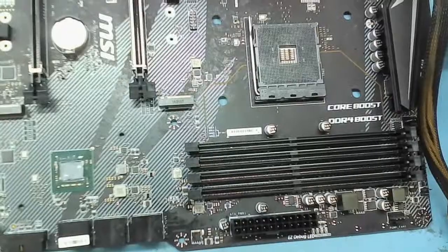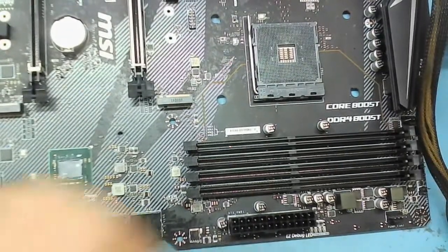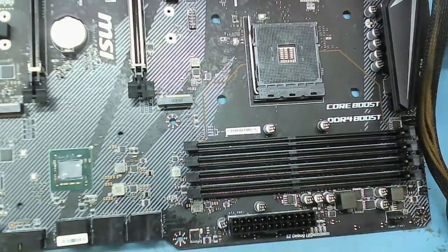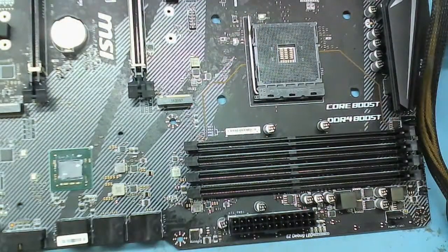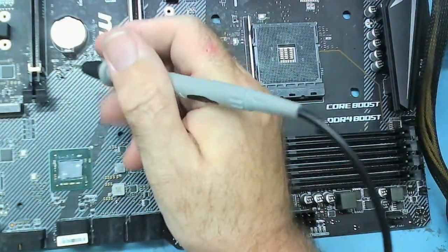Well, if you thought about it right, there's only two places that voltage can come from. One is the CMOS battery, which has got 3 volts in it, and one is a 5 volt standby on here. And in theory it could come from both. I'm telling you now, it ain't the CMOS battery, because that only powers the real-time clock, and it doesn't go through voltage regulators. I'm pretty sure, but I don't think it powers certainly 2 voltages on this. But we could be sure.